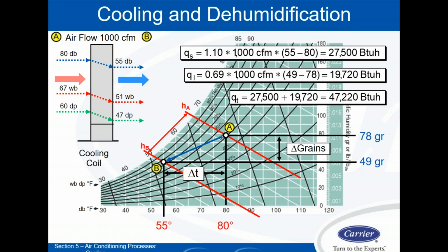In a lot of cases, especially residential nowadays, all the systems that we're putting in that have variable speed furnaces and things like that, we are defaulting the systems to 300 CFM per ton, whereas the historic number has been 400 CFM per ton. The lower the CFM per ton, the more benefits you are going to have on the dehumidification side. Once again, come join us at this afternoon's webinar and we'll talk about that a little more.